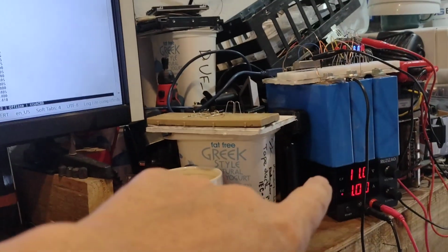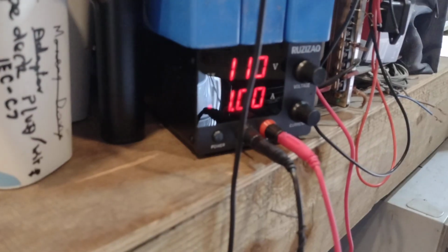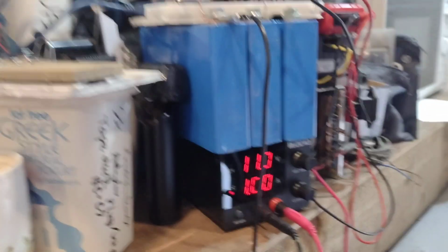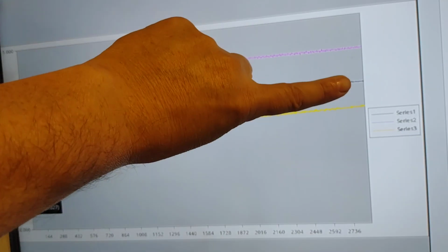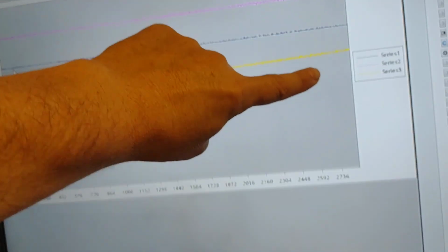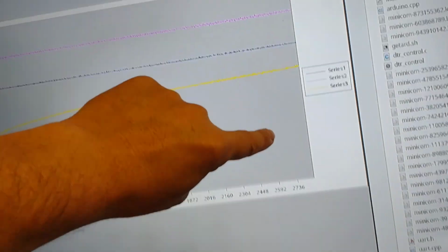and it's leveling off. Right now we're currently on. Okay, so the constant voltage I set the power pack to is 12 volts. I'm also setting it at 1 amp charge. Right now it is not going to, this is the point. You can see how these lines are different. They should be together. This is the cell voltage, and those should be the same voltage, right? And the problem is they're not.